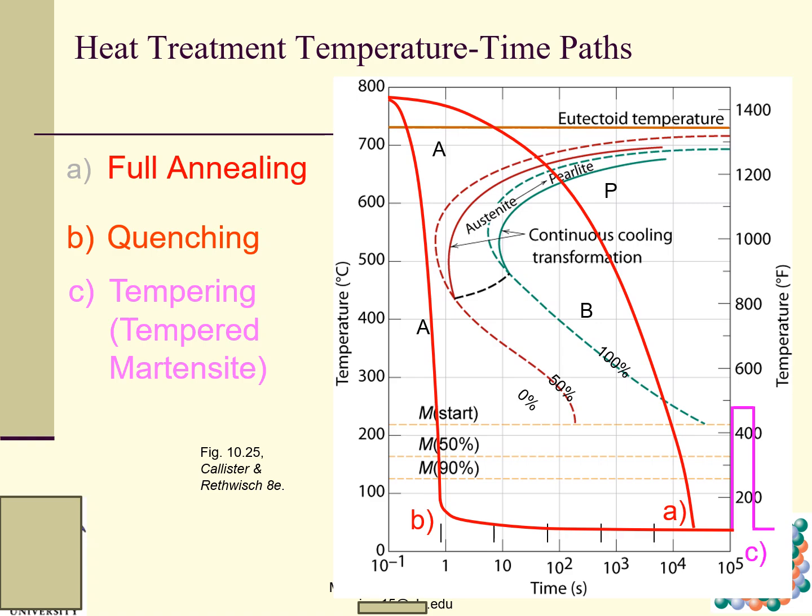So tempering. This is annealing, tempering, quenching. Tempering means that martensite itself, as I said, is very, very brittle and very, very hard, and cannot be used directly in industrial applications. However, we can do something to make it softer but still strong enough. How to do that?